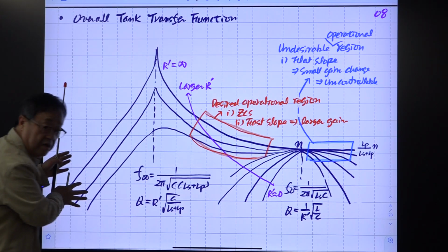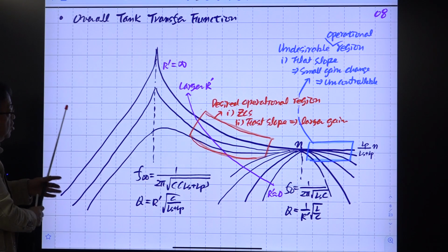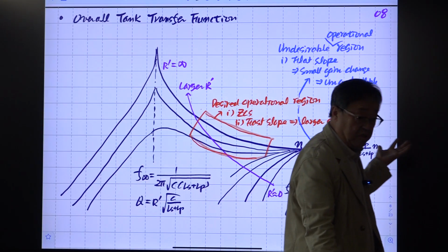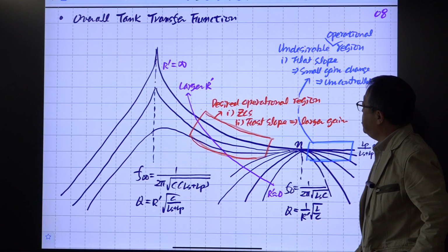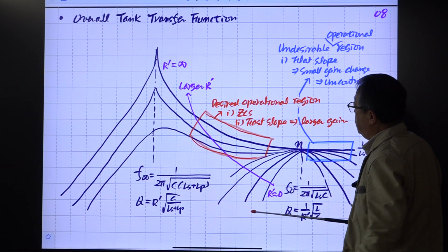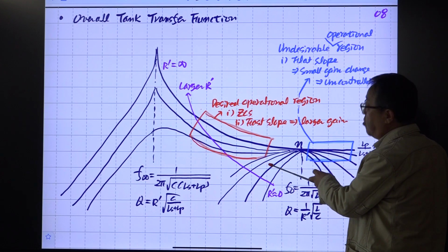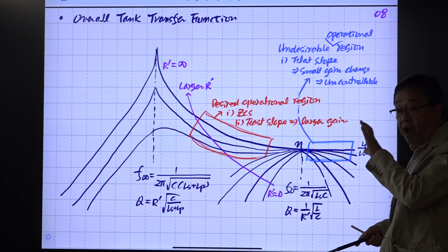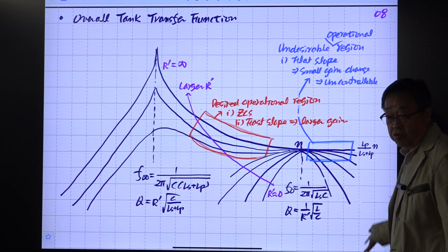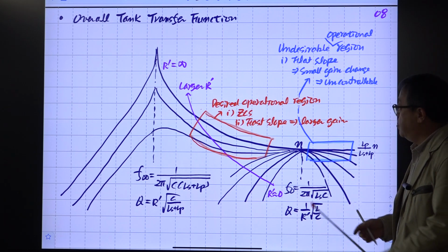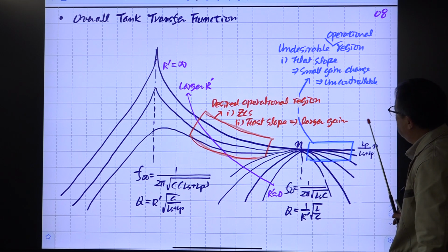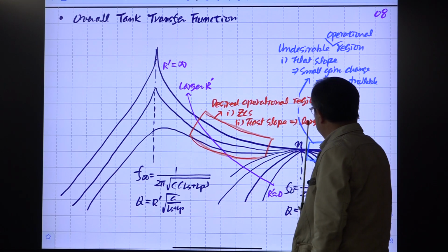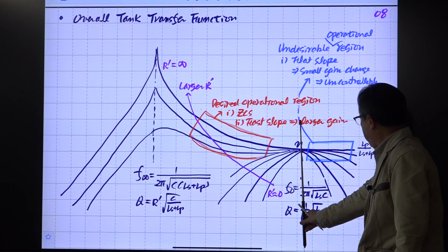This thing occurs here. But now this resonance occurs at higher frequencies because with the series connection of the L we just add L, and with the parallel connection of the L, the composite L becomes smaller, so it goes the other way around. So if you excite that resonant tank somewhere here, the voltage gain is just n.